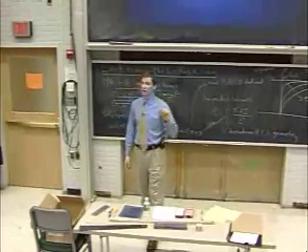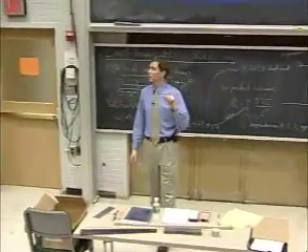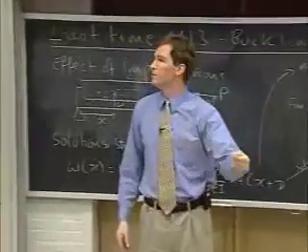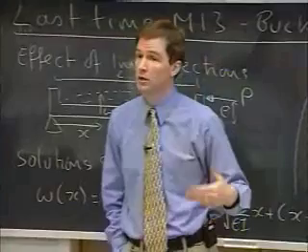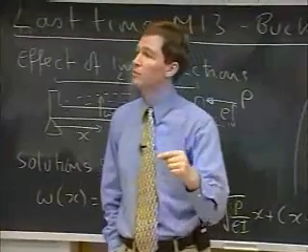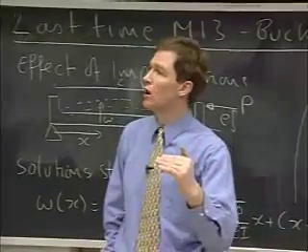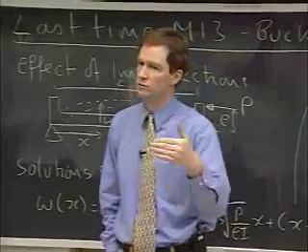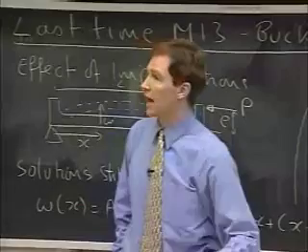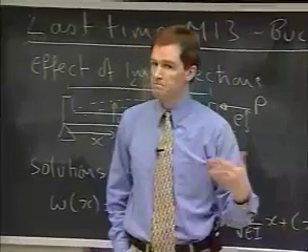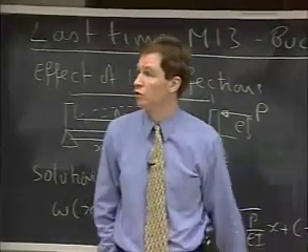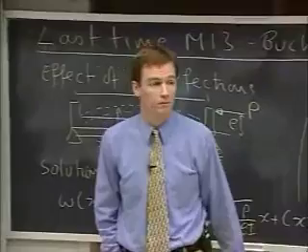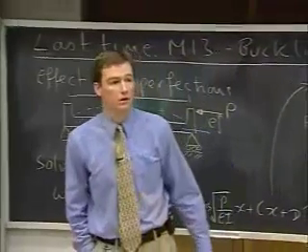So you want it to hit its design loads with maybe some small margin of safety, and that's a technical term. The margin is what the designer builds in to exceed the requirement, so that if he or she has made some error, it's accounted for. But no more than maybe 5% on the ultimate load that you're asking your structure to carry. It's an important question. Other questions?